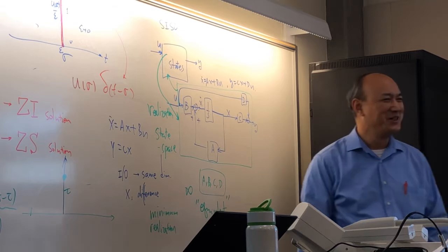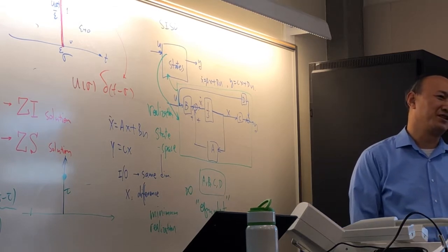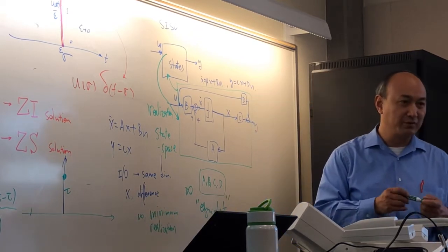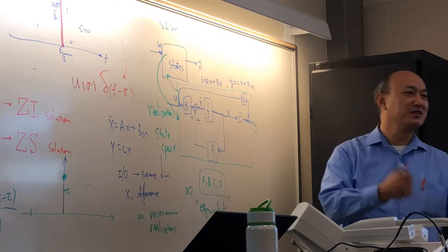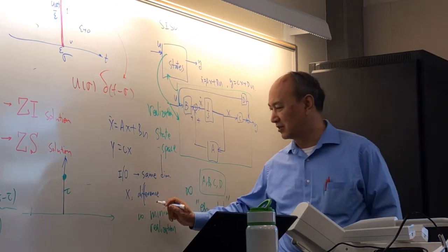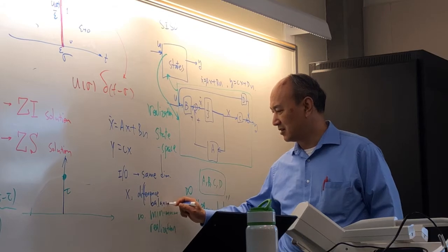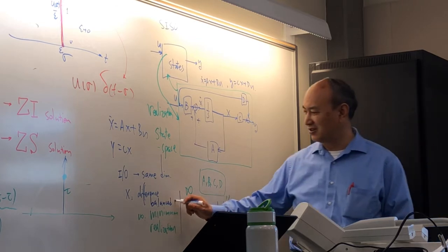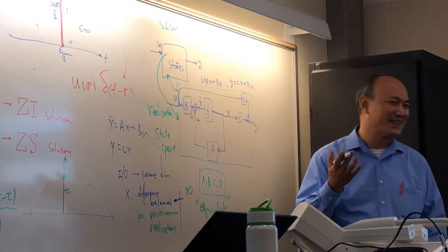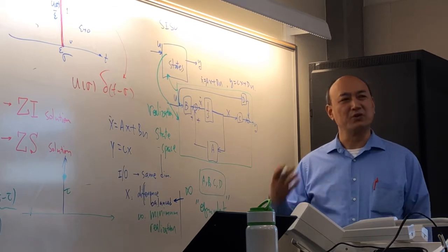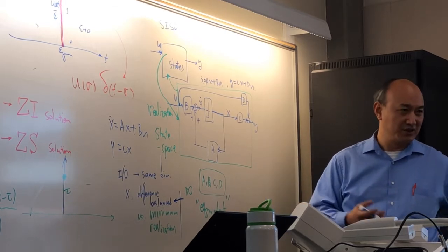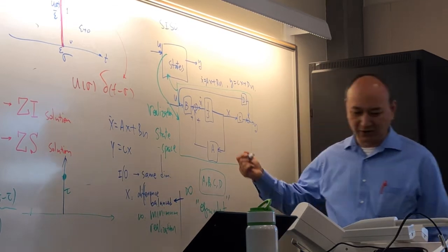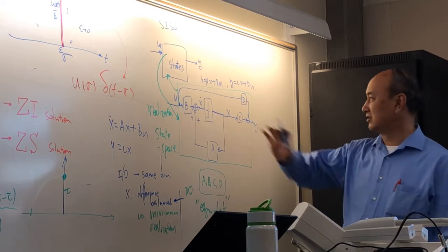Now how to make this unique, we are going to learn, is called minimal realization. But unfortunately, how many minimal realizations? Still infinitely many. How to make the minimal realization unique? You need something called a balanced minimal realization. To understand this, you need to understand in what sense we mean balanced. So we need controllability and observability, the equally observable and equally controllable. Those concepts are all connected together. So starting from here.